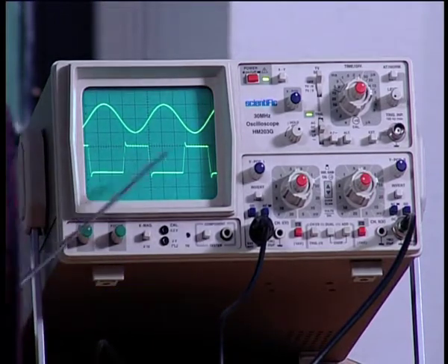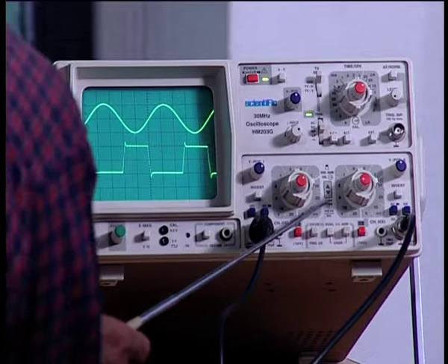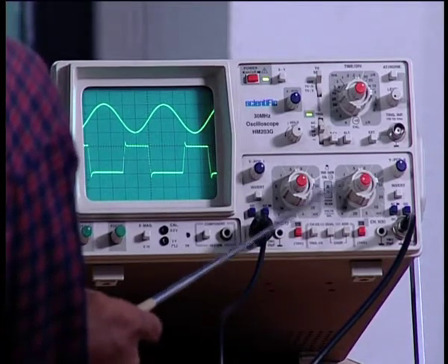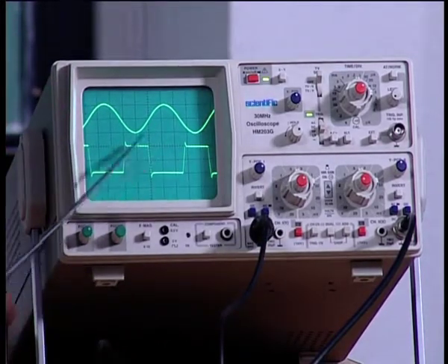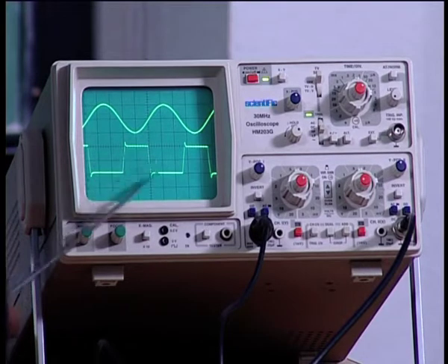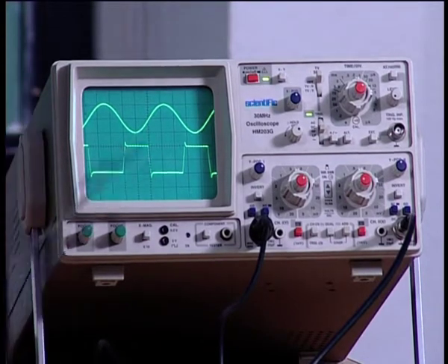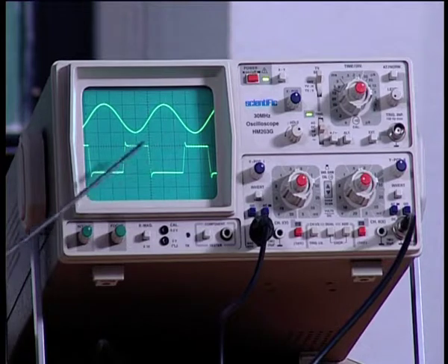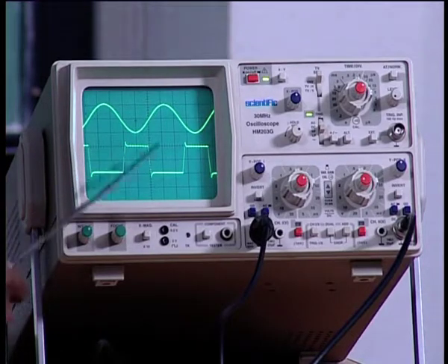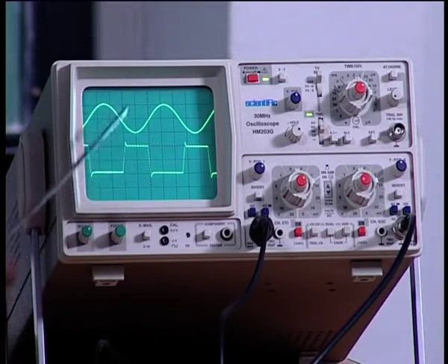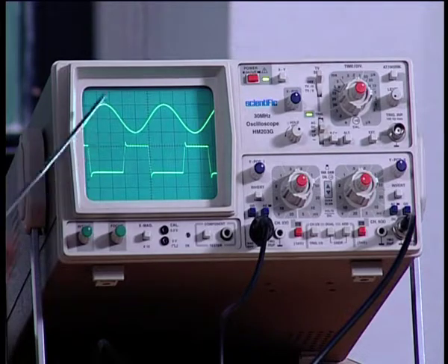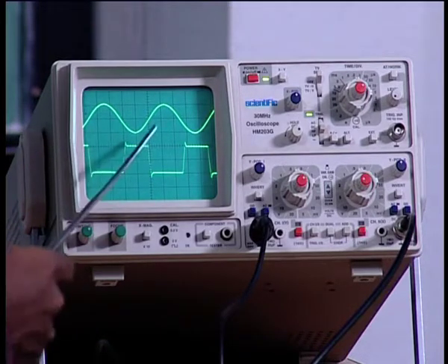If you actually look at the position here, it is 5 volts per division for the oscilloscope. So nearly more than 2 divisions are there, that means about 10 volts plus or minus is what I get here. So you can see it goes to plus VCC and minus VCC every time the sine wave crosses the 0. So this becomes a 0 crossing detector, and it is therefore also called a Schmitt trigger, because a sine wave is converted into square wave.